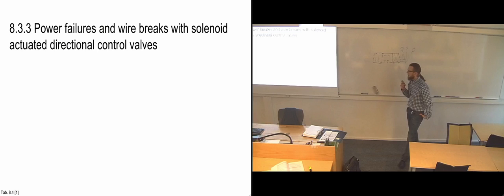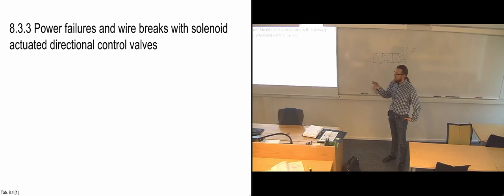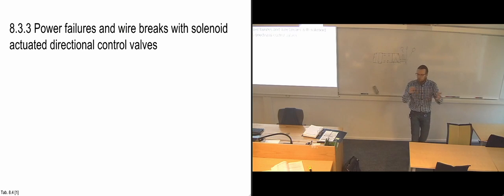But you also have closer possibilities, like a wire break. If you get a wire break inside your system somewhere, it's a bit more difficult. Then you really need to go in with experienced technicians and start figuring out where exactly the wire break is, because it's not always possible to actually see where a wire has broken. If you can see a wire that snapped, then that's okay, because then you know that's the problem. But it might just be that a wire in one of the connections has a bad connection, and that's really difficult to see if you're not experienced and don't know how to search for failures in it, basically.